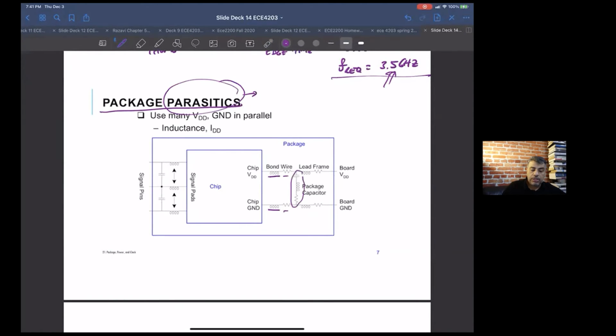Those are not perfect. Maybe I should come back to this. But anyway, you have parasitic inductive coupling between wire bonds, and this is self-inductance. By the way, especially on printed circuit boards now, when you're doing high-speed designs, this is especially bad news for computer engineering guys: you're going to have to worry about RF and microwave problems a lot more than you would like.